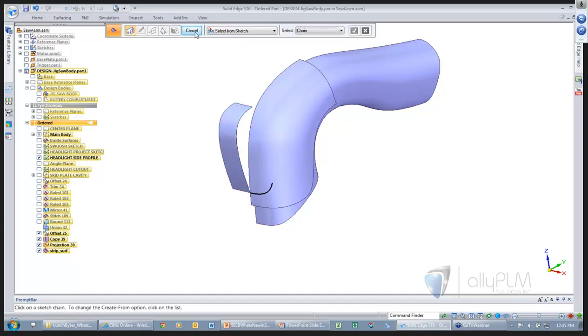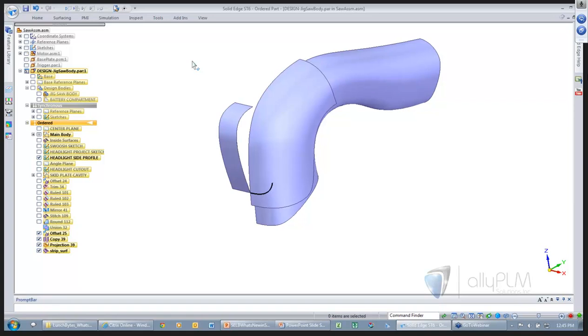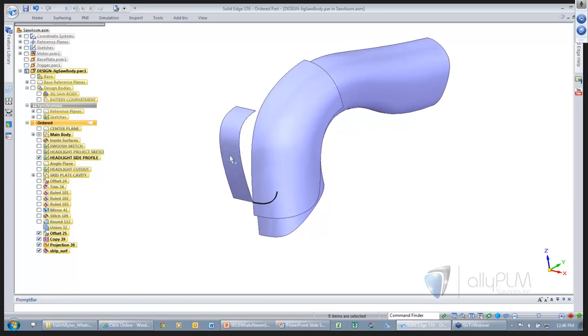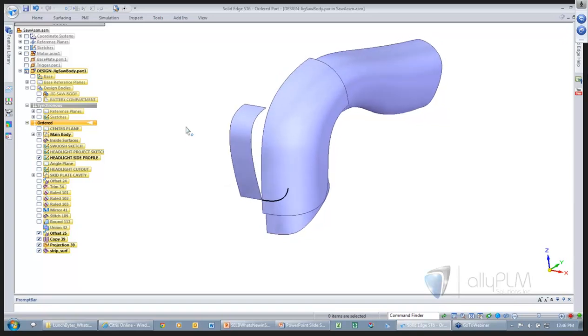Okay. What this is going to do is this is going to be a construction, and I mentioned on the slides about controlling continuity, whether it's curvature continuous or tangent continuous. I'm going to use this strip surface to create that tangent continuous shape, which you'll see a little bit later. So this is strictly for construction.